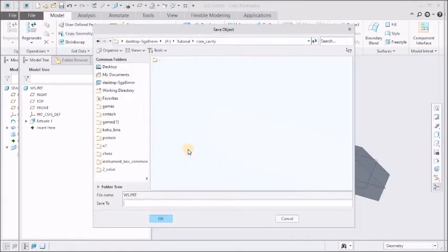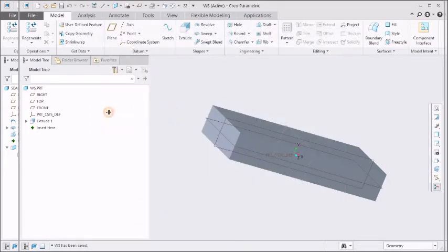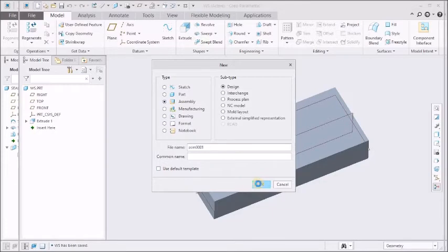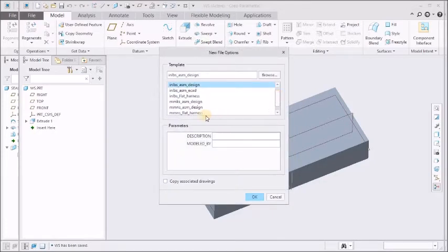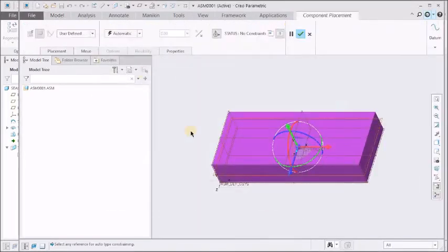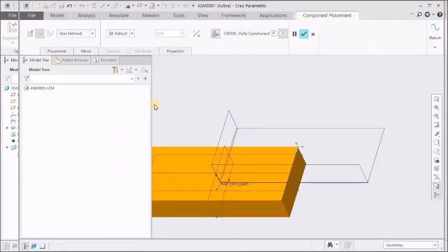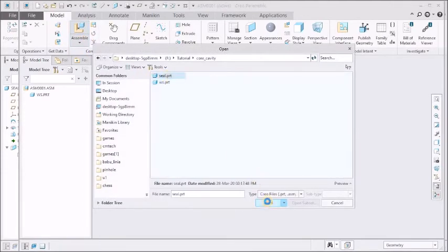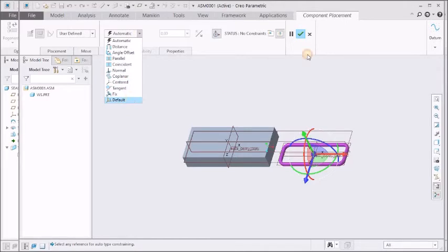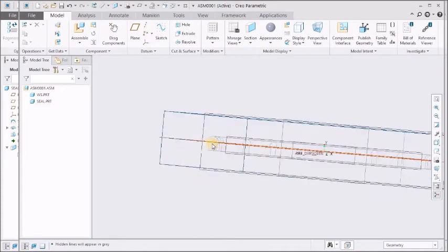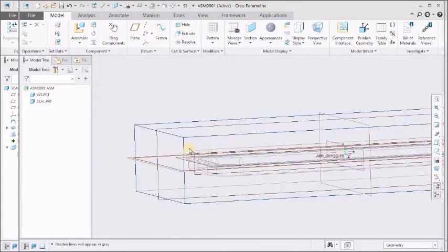Now this workpiece has been created, so the next operation is to create an assembly, using the millimeter Newton second assembly design. In this assembly I will first bring the workpiece and set it at the default location, and I will accept that, and then I will place the seal, again at the default location. So this seal has been placed over here. If we see it in hidden line, we can see the seal has been placed.